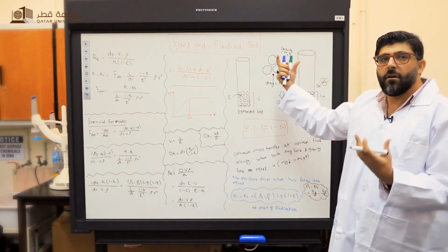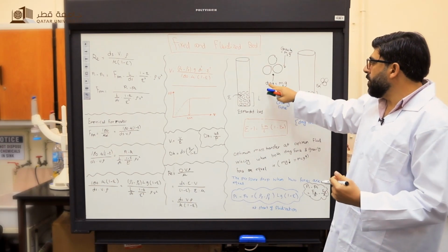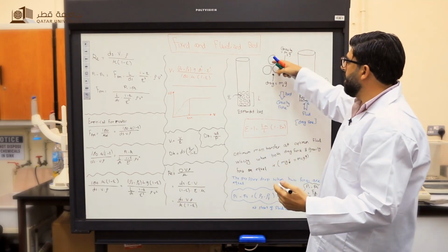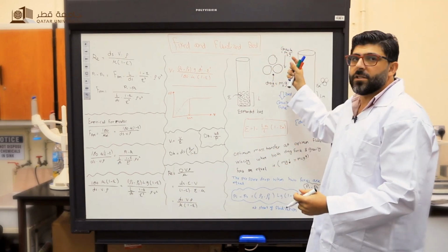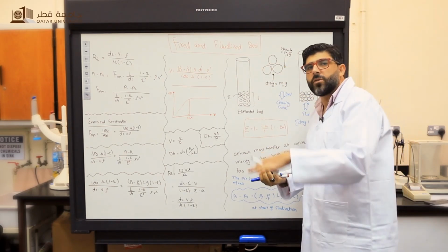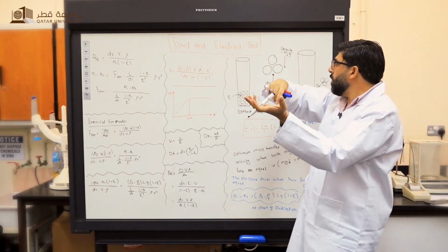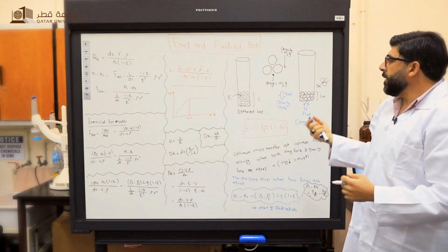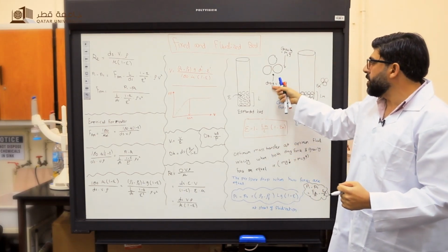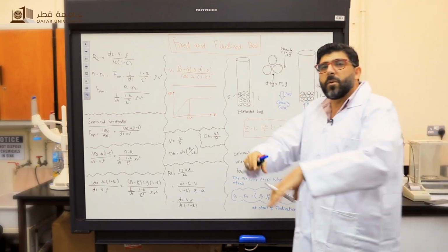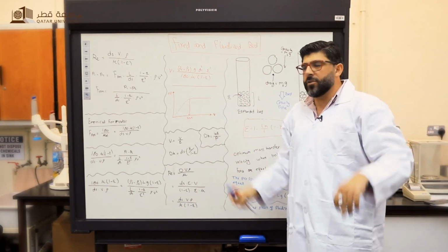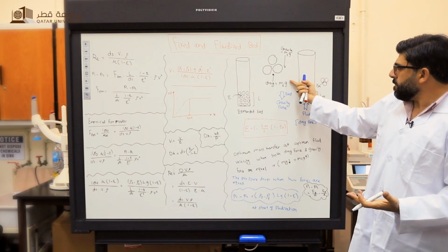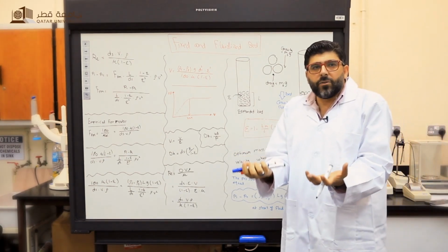We have the particles, and there are two forces. The drag force from the fluid, from down to up, drags the particles and forces them up, and we have the gravity force, due to the weight of the particle, which forces it down. If the drag force is higher than the gravity force, the particles will be fluidized. It will be like flowing through the medium. And if the gravity is more than the drag force, the particles settle down, and it's called fixed.